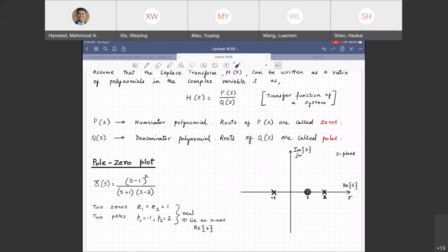So as we change our system, we will track the movement of the poles. If they start in the left half plane, and stay within the left half plane, then that indicates that no matter what you change in the system, you will be stable. But if you start with the system stable, with the poles in the left half of the plane, and you tweak something in the system, the poles will move, and you can track that movement.